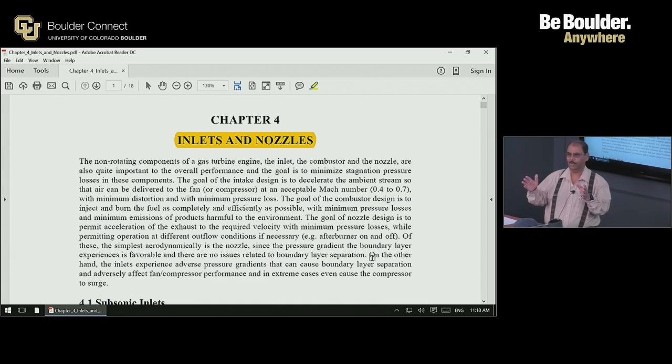Does it have to be a narrow body or a wide body? Because if you make it a narrow body aircraft, it will become too long, okay? And therefore the embarkation and disembarkation times are going to be much larger because of a single aisle. As you increase the number of passengers, twin aisles are better for loading and unloading.